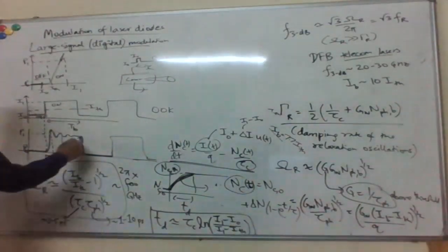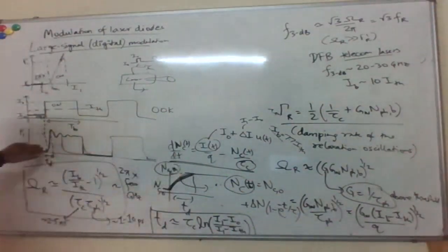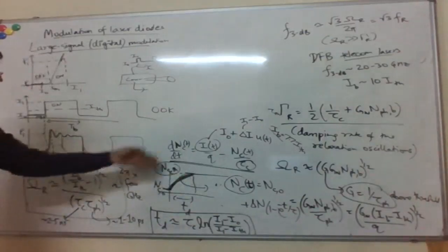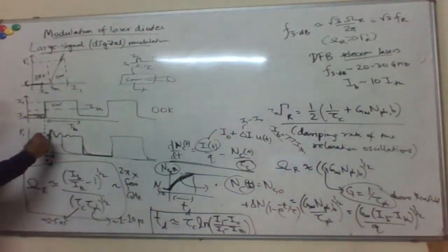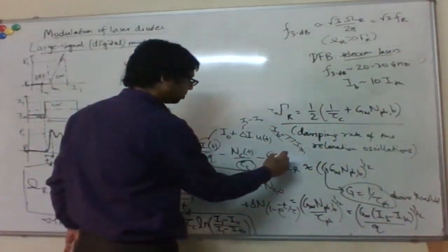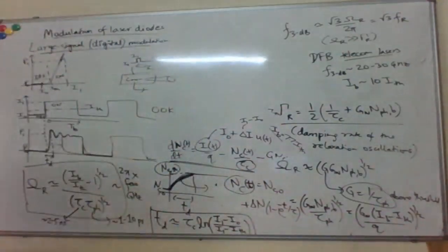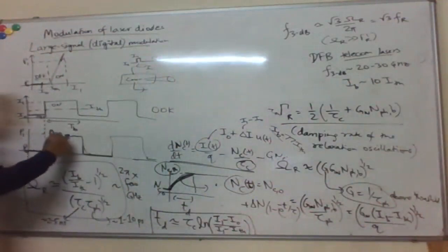Okay, and similar dynamics also happen when you turn it off. So not only this rise time, right? Once the carriers rise, then also the photon number rises, and then we have this feedback between the photon and the carrier number, and you get these oscillations. Okay, so for that now you need to include this next term also. So then now it becomes more complicated, but yeah, you can numerically solve that and get this response.